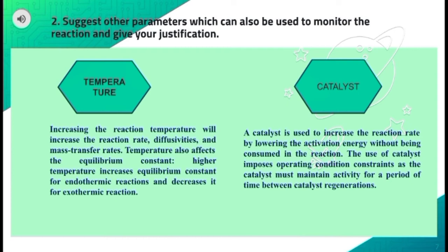In this slide, I will present the other parameters which can be used to monitor the reaction in a plug flow reactor. The first one is temperature. Increasing the reaction temperature will increase the reaction rate, diffusivities, and mass transfer rates. Besides that, temperature also affects the equilibrium constant, whereby a higher temperature increases the equilibrium constant for endothermic reactions and decreases it for exothermic reactions.